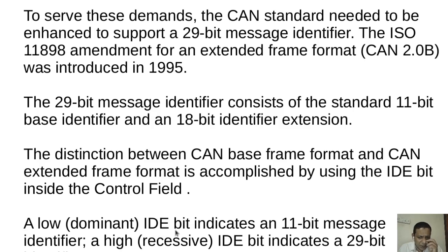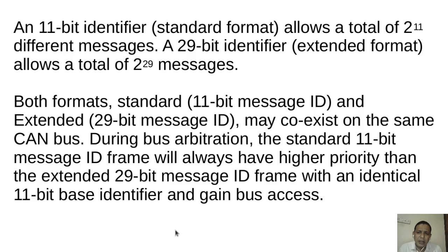Based on that bit, we can decide whether it is the standard frame or the extended frame. The standard frame has an 11-bit message ID, and the extended frame has a 29-bit ID. Both will coexist on the same bus.